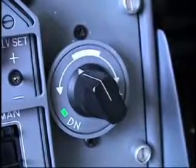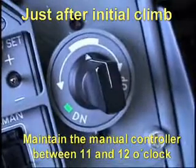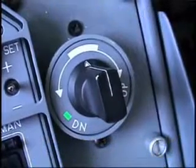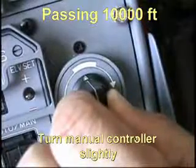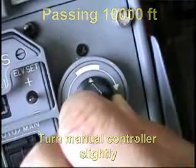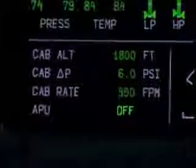Just after the initial climb, maintain the manual controller between 11 and 12 o'clock position within the null rate mark, so as to achieve a null or slightly positive rate for the cabin altitude. Passing 10,000 feet pressure altitude, turn the manual controller clockwise. Identify the resulting cabin rate. Usually 400 to 500 feet per minute will be good for this situation.